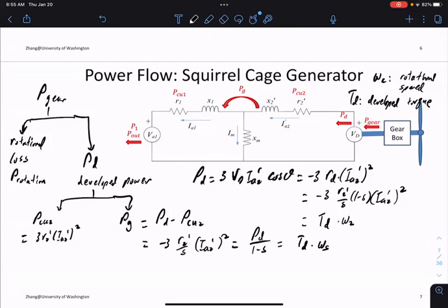At the secondary side, it's going at a slightly faster frequency. Once it goes through the air gap, it spins at synchronous frequency, so your power goes down because you have reduced the rotation speed. That's another way to think about PG. That's why air gap power is a useful number: it's directly related to the developed power, the torque, the slip, and the frequency.